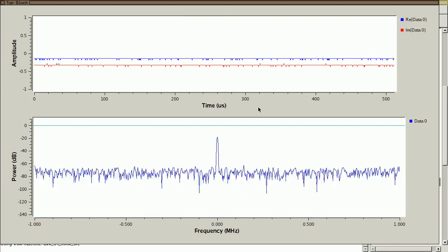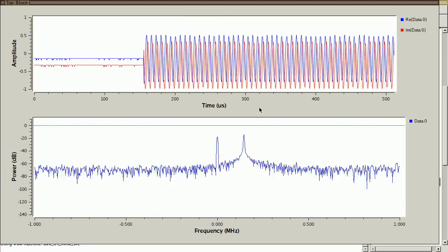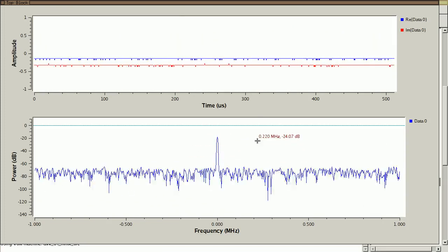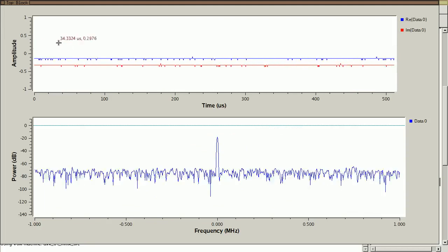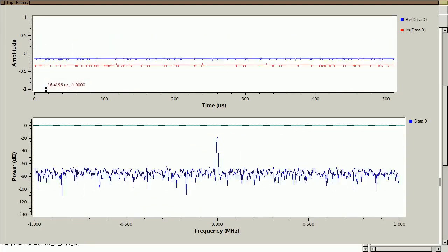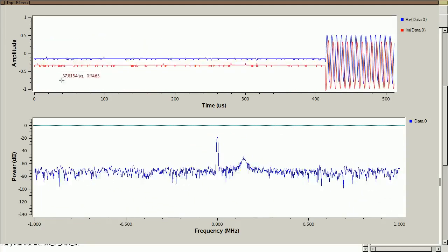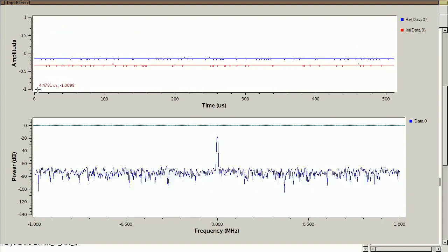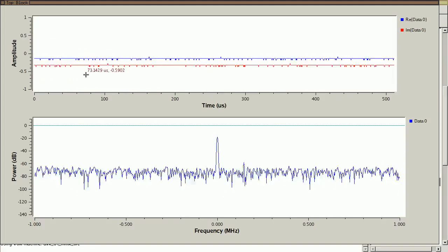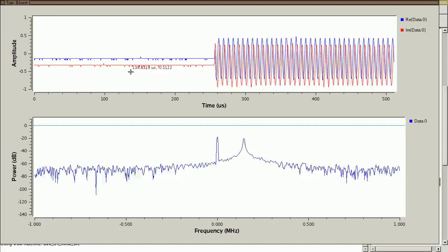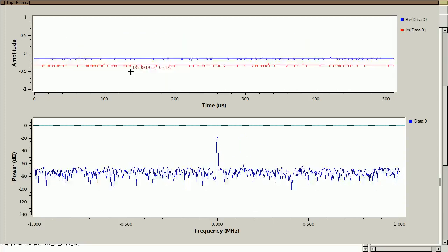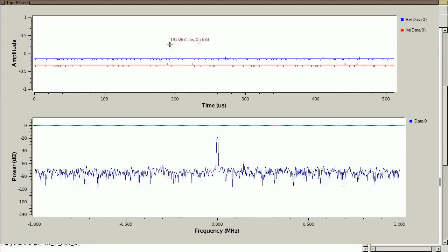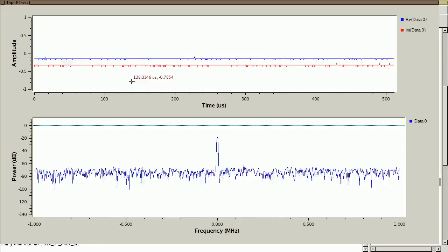Things look pretty much the same, except notice that in the FFT sink, everything has shifted up a bit, and in our scope plot we can see that the sample values are in fact extending from about 0.5 to -1. If we were to remove the DC offset or just shift it up a little bit, we could even gain a little bit more dynamic range, but not a whole lot. Now we're using most of the full scale that is available to us.